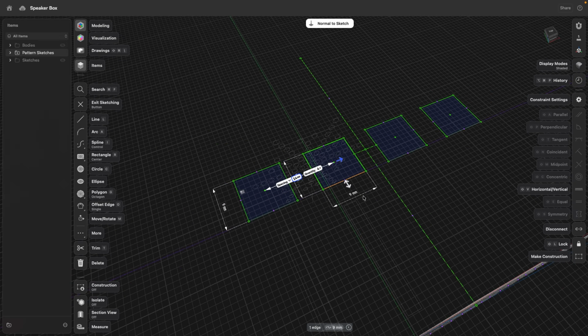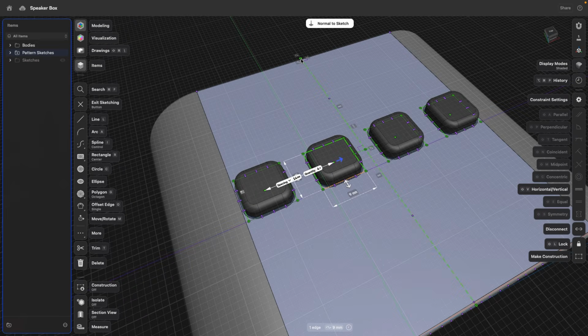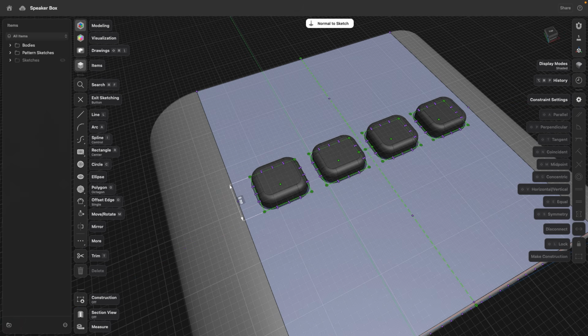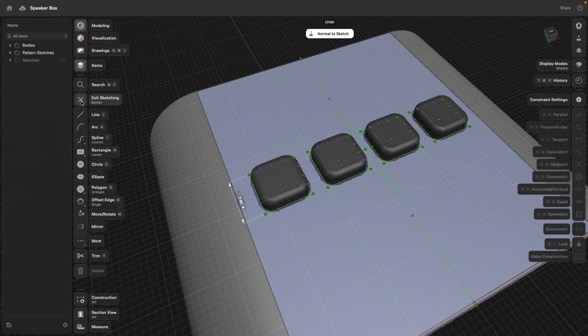But then I positioned this linear sketch pattern by drawing these four lines and snapping them to the midpoints of the face. And this then allows me, when I change the linear pattern, it grows and shrinks always towards the midpoint of this face. And even when I change other values of the geometry of what I pattern, you see then the holes change and also the buttons change.